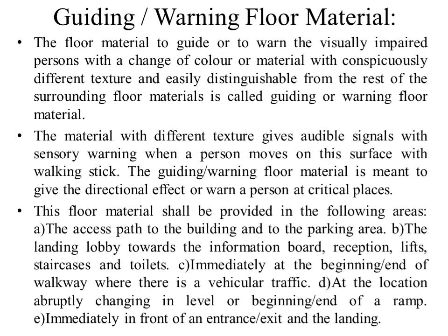Then guiding and warning floor material. The floor material to guide or to warn the visually impaired person, with a change of color or material with conspicuously different texture and easily distinguishable from the rest of the surrounding floor material, is called guiding or warning floor material. The material with a different texture gives audible signals with sensory warning when a person moves on the surface with a walking stick. The guiding floor material is meant to give the directional effect or warn a person at a critical place.